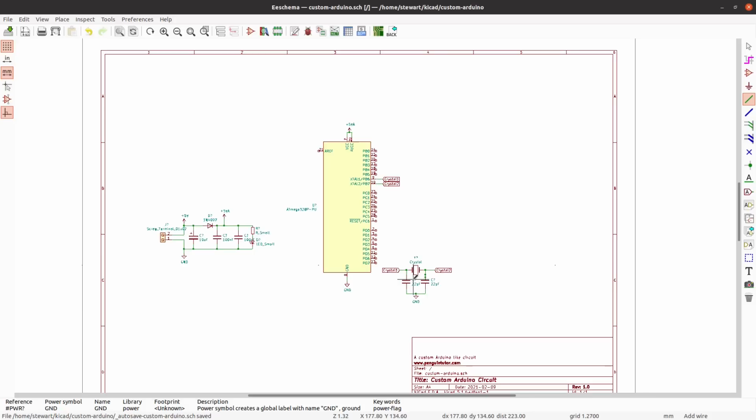Now on the normal Arduino board, the UART will be mounted on the Arduino. We're going to use an external UART that can be plugged in as required. Program it, then you can remove the UART. You don't need to use those components. So like we did with this, I use a screw terminal here. I'm going to use a pin header so that we can plug the wires that go to the UART, using DuPont type connectors like that.